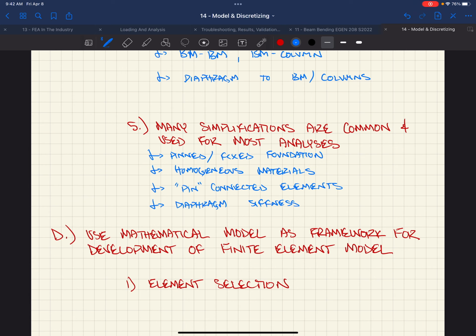I'm still confused about how you modeled it. I put it in VA. You're saying that it's like a continuous beam versus 2 simply supported beams, and so it attracts more load because there's moment transfer over the hinge? There's no hinge there, right? There's the model where this is 2 simply supported beams, basically 2 bays of diaphragm. That would assume that there's no connectivity. We've got a big hinge here. If you assume that there's enough connectivity there, right, you might suck more load to that center.